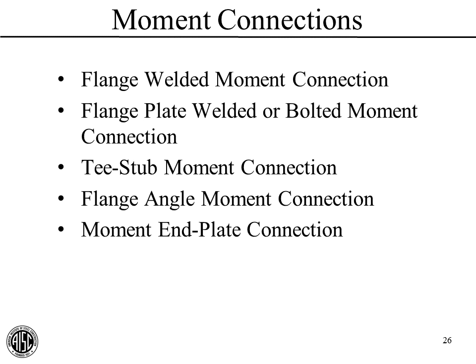All right, now moment connections. We have these 5 categories in the AISC manual. We have flange welded moment connections, flange plate welded or bolted moment connections, T-stub moment connections, flange angle moment connections, and moment in plate connections.